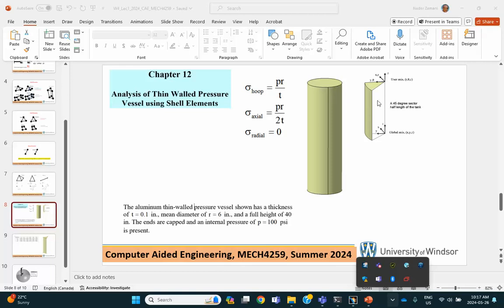When you pressurize, this whole thing will fall apart and just move away as a rigid body. Even if you created a solid object, an extracted solid like the grayish one in the part design, and then extracted the top surface and the side surface, you will have to join them, because otherwise these surfaces do not talk to each other.